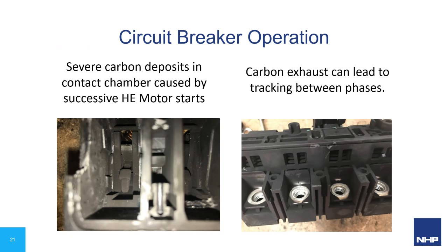Firstly, this part of the motor start characteristic has no impact on thermal current settings of the circuit breaker or the motor overload. Secondly, it only has a small impact on the magnetic settings or the characteristics of the thermal magnetic circuit breakers. It has no effect on the settings of electronic overcurrent relay breakers, MCCBs. The major effects are on the contact sets of circuit breakers of all types, and of course of motor start contactors. So let's look at a couple of the findings that we have from the mining industry in Western Australia.